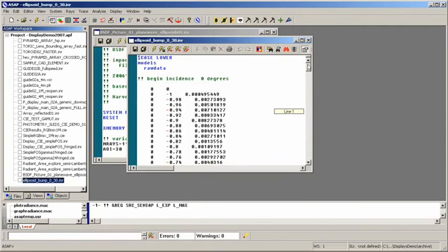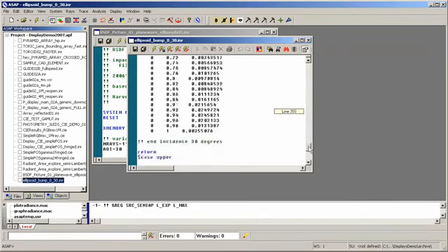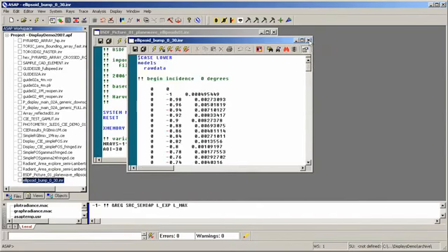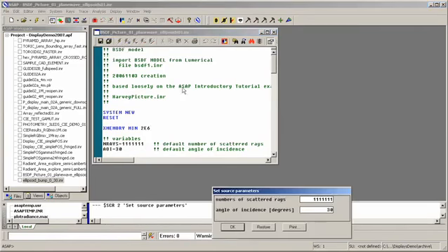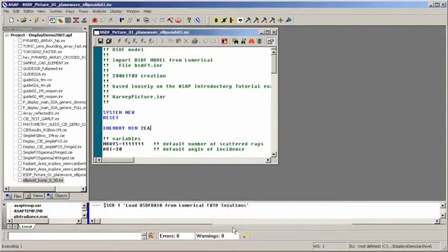Lumerical actually wrote my raw data functions or raw data models, which will be used to generate a BSDF function for ASAP. And now I'm actually going to do that. I'm going to run an ASAP model where we scatter rays off of that and take a look at the output result. We will create a 2D and a 1D slice of that distribution through the plane of incidence. And those will give us a good idea of how well we have transferred data from the numerical application to ASAP.